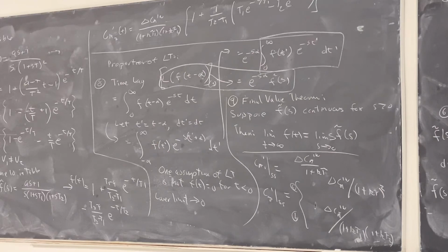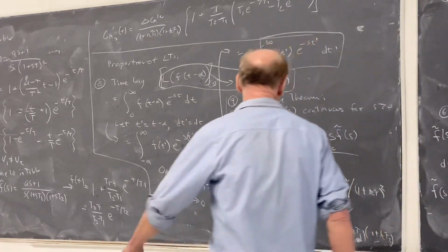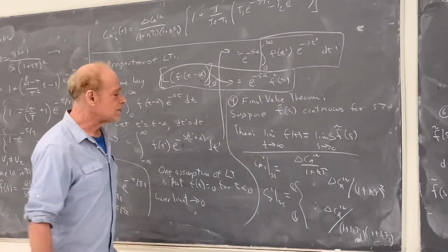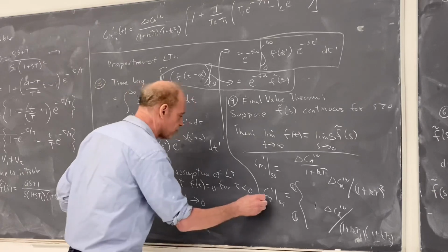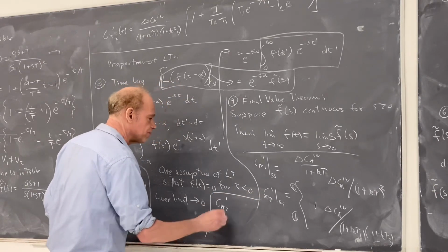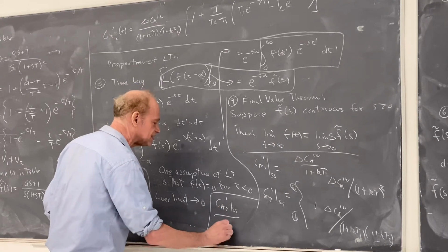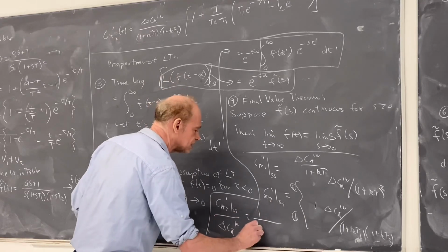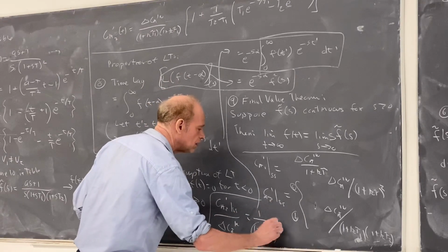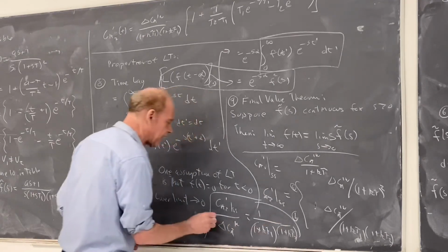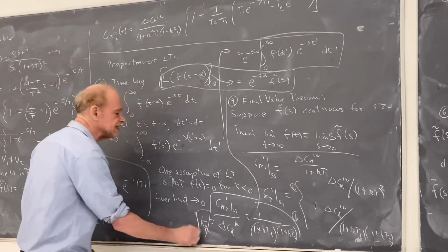So it tells me that this coefficient here is the steady state value. And notice the last thing before we finish, CA2 prime steady state divided by delta CA in, which in this case is 1 over 1 plus k tau 1, 1 plus k tau 2, is what we call Kp, the steady state gain.